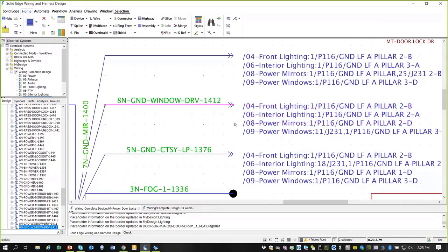This is an example of styling that your team gets to set up. So you get to set things like what font do you want to use? What's the offset from the wire end where you want to place this text? What details do you want in this? You get to pick that based on your company standards for efficiencies. That way, all the designs would look the same. We set all of this information in what are called style sets, and the tool makes this real easy for us.